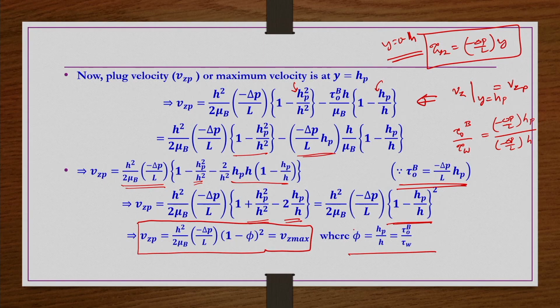So, because of that, for most of the problems associated with viscoplastic fluids, we have used a trial and error approach, like the Hanks model or the Slater model. For the case of pipe geometry, we have seen that a trial and error kind of approach is required, or some kind of analytical expressions are required. Anyway, let us not worry about that one.